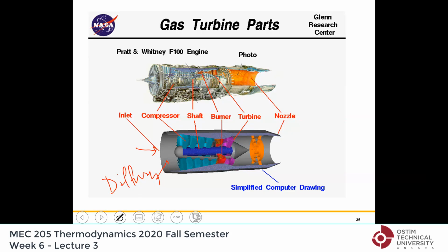And then this is the compressor, schematically, as you see here. And then the burner or combustor right here. And we generate a little work to run the equipment, so a small turbine here. And this part is the nozzle, as you see. The area gets smaller. So here you have high velocity gases leaving and producing the thrust. In the land gas turbines, you don't want that. But if you are on an airplane, this is what you want, together with the work generated there.